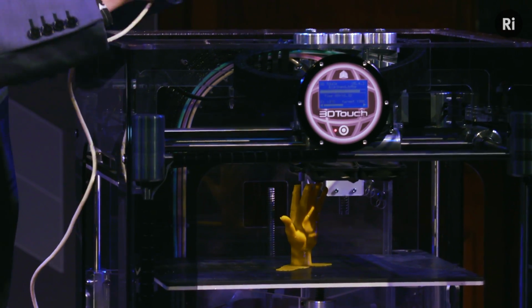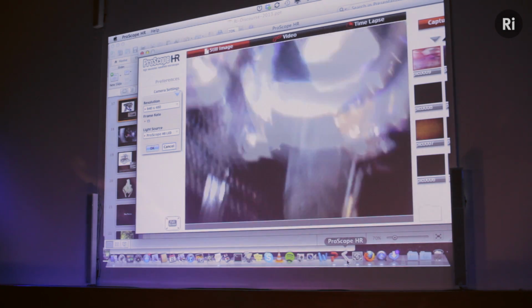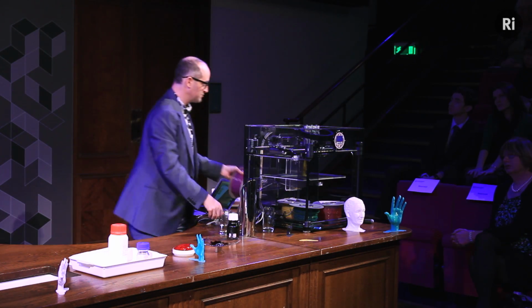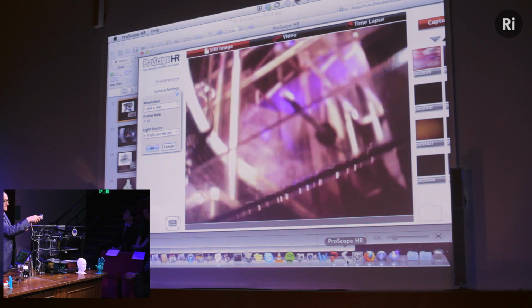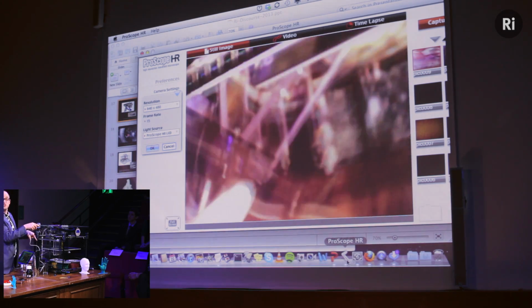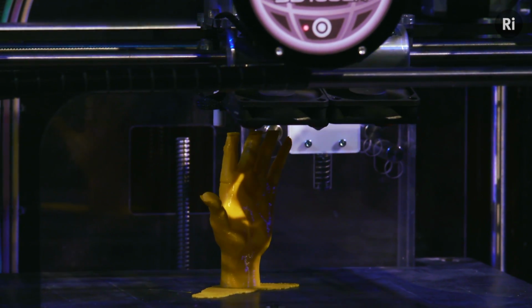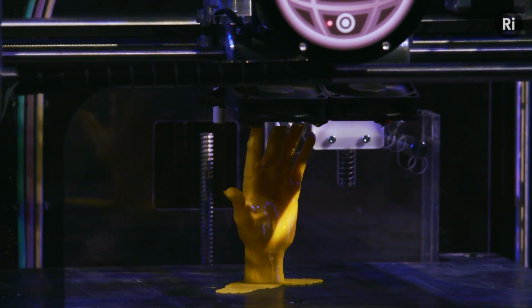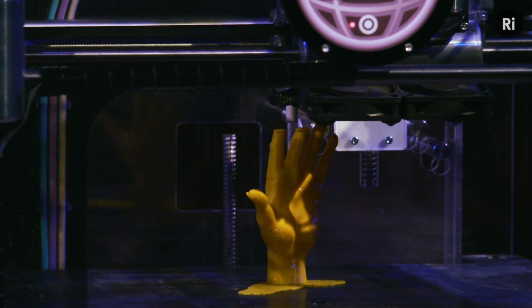Well, that's kind of remarkably simple too. Up here, you can see something whirring, and that's turning a bit of screw, which is pushing a little bit of this material through into the nozzle below, and the nozzle is heated up, and they heat it up to twice the melting point of the material, and that squirts it out onto the bits where it knows it should squirt it out, and it doesn't squirt it out, hopefully, on the bits it shouldn't. And then, because it's twice the melting point of the material, it heats the bit below, which was printed, let's say, a minute before, and that allows the two to bond really well.